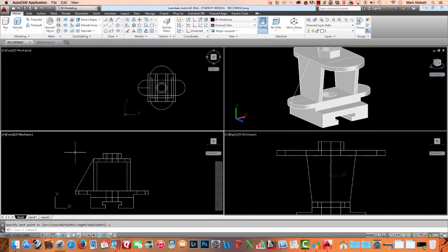Okay, so that puts a polyline right there, dead center where it's supposed to be, and the offset or the thickness of this object is supposed to be 0.3. So basically, if we extrude it 0.3, we're going to have to move it back 0.15. So I'll go ahead and do that.